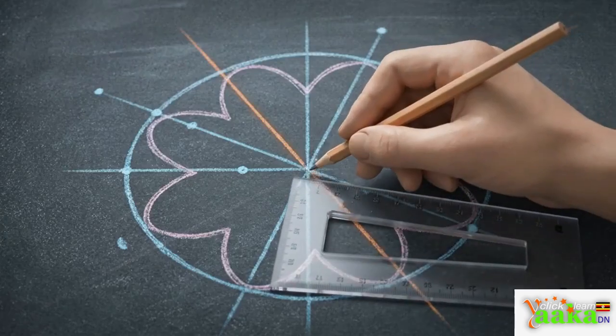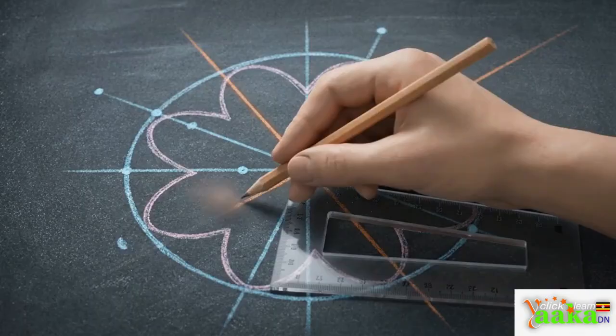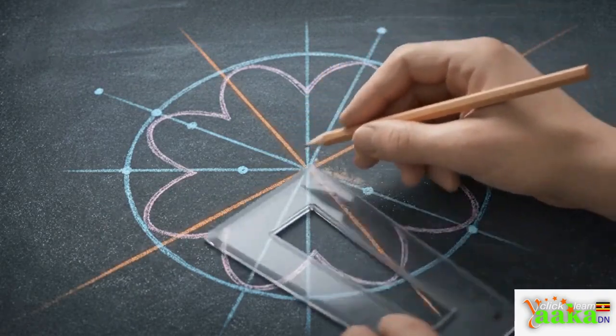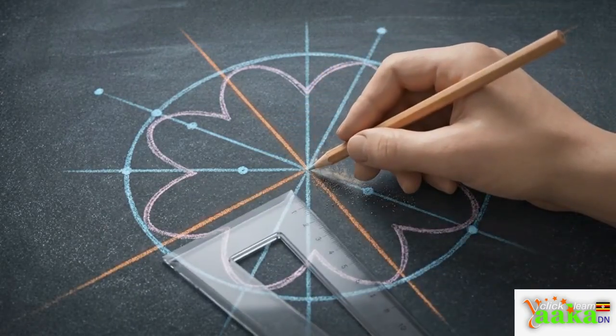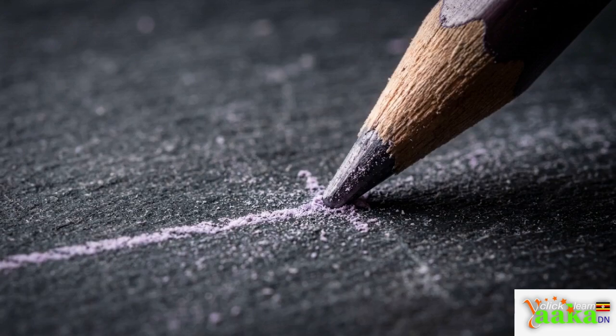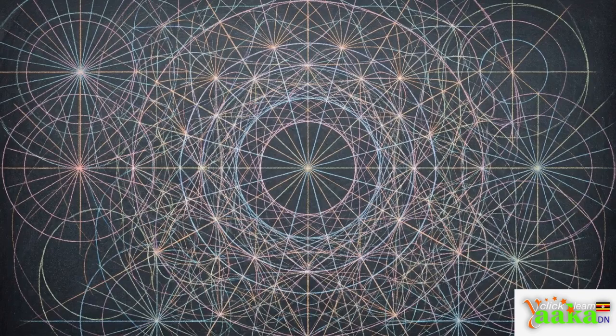To guide our next step, draw straight radial reference lines outward from the center of the base circle, passing through your 12 center points. Maintain very light pressure with your H pencil. The page is about to become heavily populated with lines, and keeping them faint is essential for clarity.